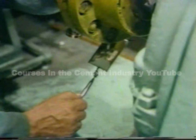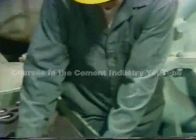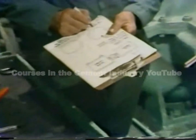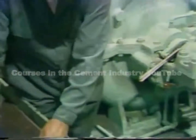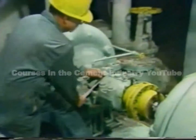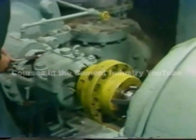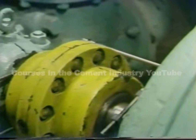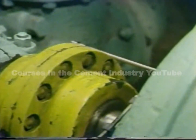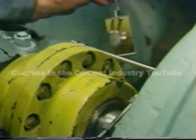When starting from zero, counterclockwise movement is a negative number and clockwise movement is a positive number. The last set of readings is taken after moving the shaft another 90 degrees. Remember, each time you rotate the shaft, it's very important that you take the readings at the marks you made. Once again, the inspection mirror is a handy way of reading the dials when they're facing away from you.